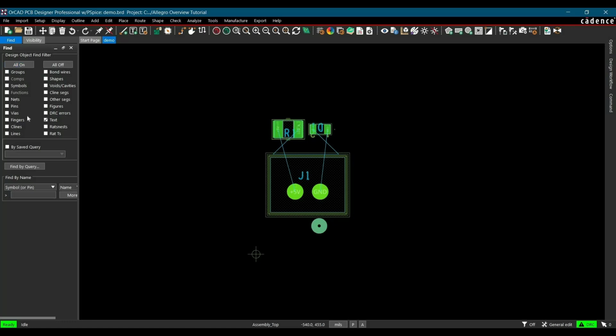So you can place it by selecting all these text together. Assembly top we generally place over the component, and designator we place outside the component. So let's do that quickly. As of now we have placed the reference designator, and we got to know how to use text block for each text.